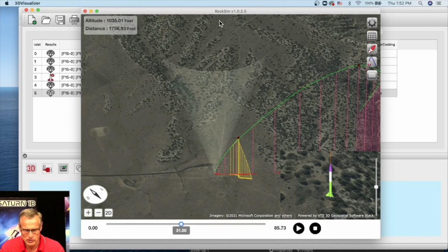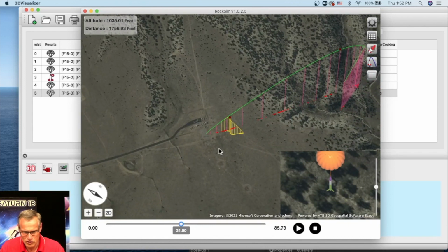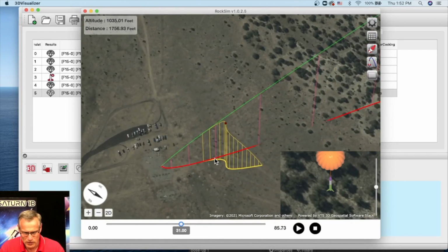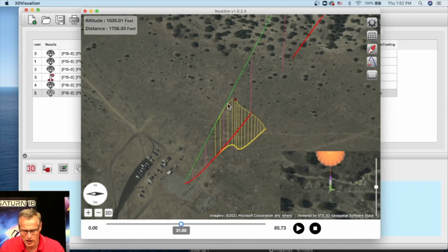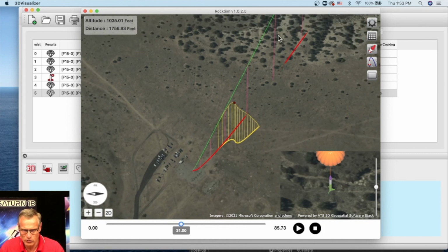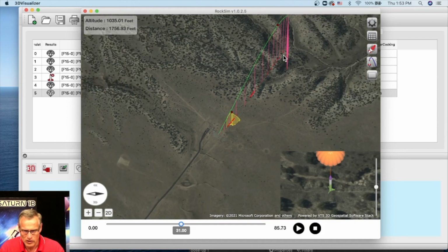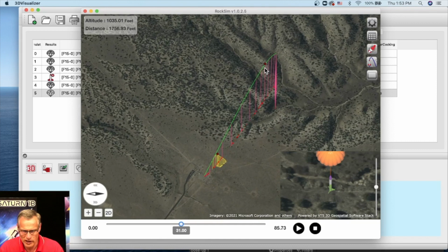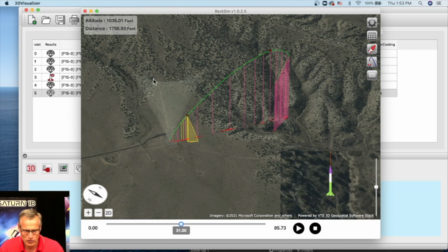Let me close the preferences. If you look at the ground track, it kind of circled around a little bit. It was kind of gliding again. And you can also see we also have a dot here. So the red dot tells us we're outside of the cone. And I'm pretty sure our green one, on the green trajectory, will also be the same. Another red dot. We're way outside of the weathercocking cone. So here's our weathercocking cone right here. So we're way outside of it.